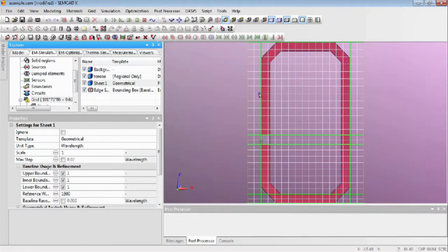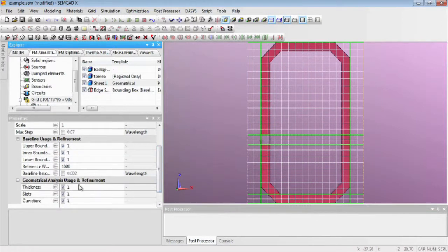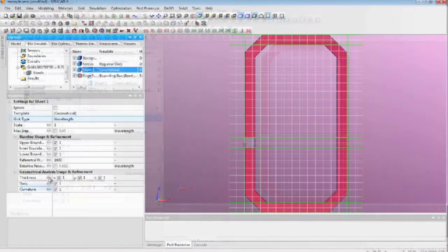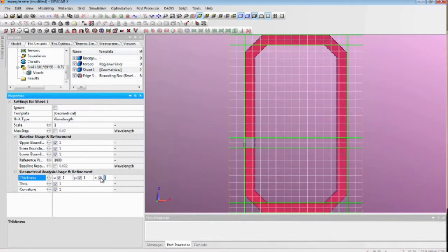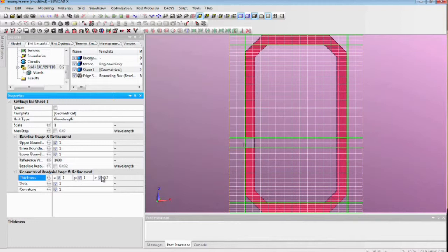And what we might want to do here is basically change the number of cells resolving the thickness of the loop, or the width of the loop. So that's a very classic example here. So now we can basically go down to our thickness parameter. And again here, we might just want to do this in the first step. Let's start with just the Z-axis. So I'm going to open the ganging properties. But essentially this allows us to address certain areas of the geometry without actually resolving the grid in a total region.